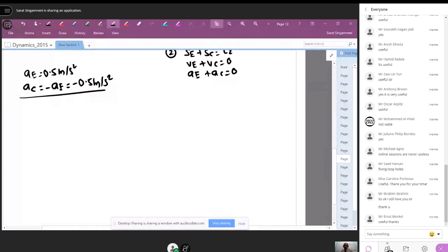With that, you can go to the free body diagram of mass 2. Call this tension T2. Its weight is 100 times 9.81, and it is coming down with 100 times the acceleration of C. So we can use sigma F_y equal to mass times a_C.